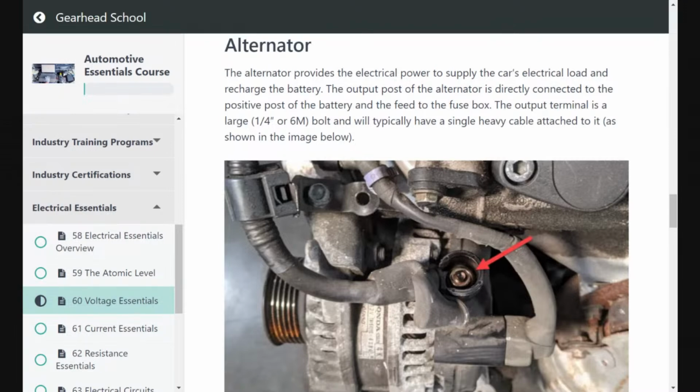There may or may not be a master fuse in there. So you always want to make sure you disconnect the battery before you go change an alternator out, because on the bottom of the car, you take this output post off, you take this cable loose, and it gets away from you, and it's still hooked on the battery at the other end. It can be pretty spectacular. So that wire off the output post of the alternator goes straight to the battery positive post.